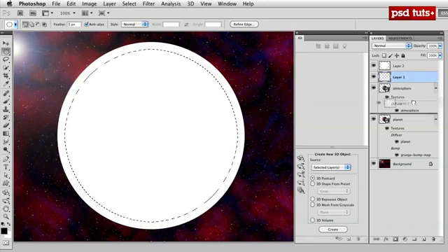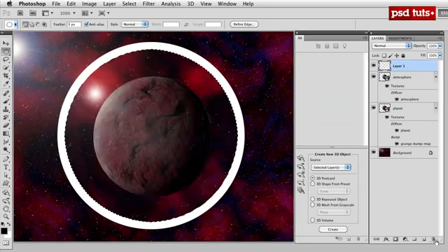So let me drag Layer 2 to the trash can, and you can see I've punched out, and we've made our ring. Right? So I made two selections, punched out the smaller circle through the larger one. Now I can deselect. This is going to be our ring. How am I going to do that? I load it as a selection by Command or Control clicking on the layer.